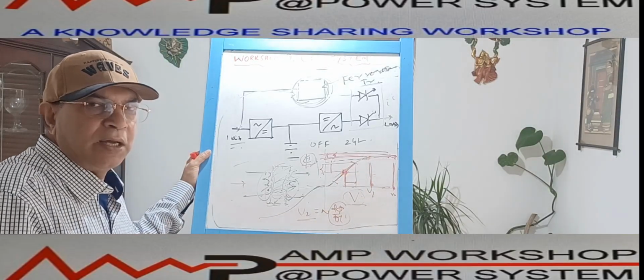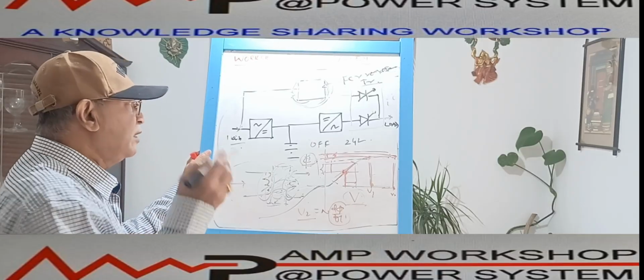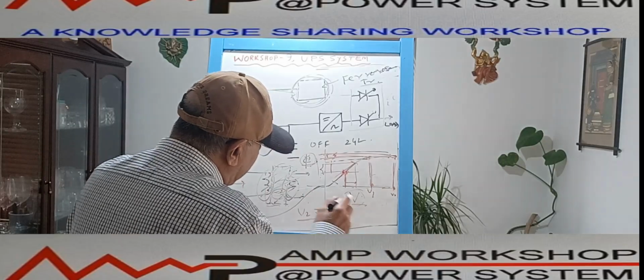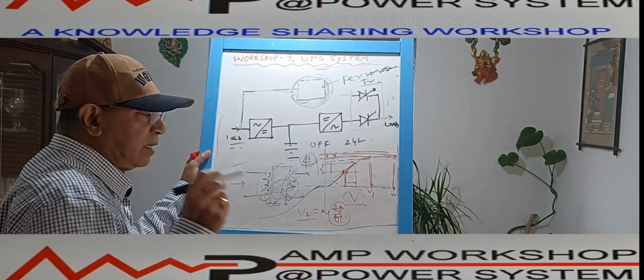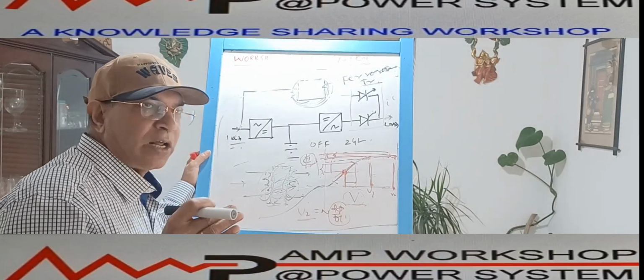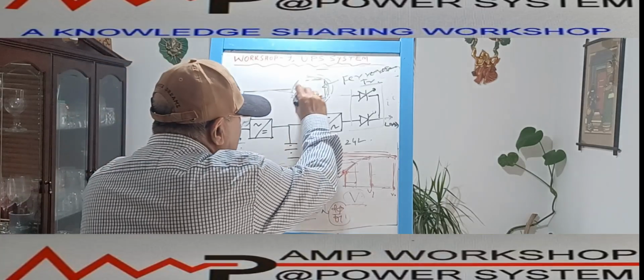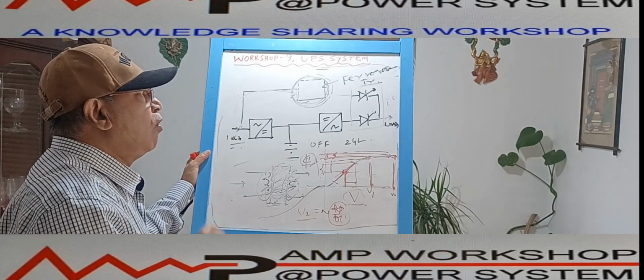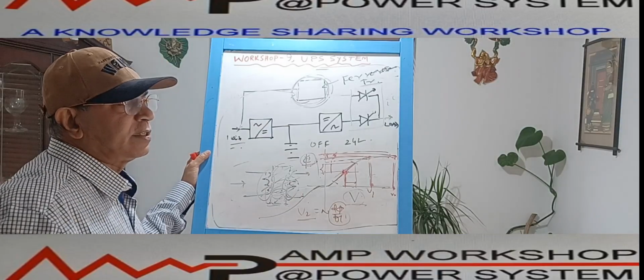That heat also has to be eliminated from the UPS system through the fan, and that is a loss of energy. So from the electric bill point of view it will not be preferred, but if the load needs constant voltage and pure high quality power, in that case we have to use either a buck boost transformer or a ferroresonance transformer in the solid state UPS system design.